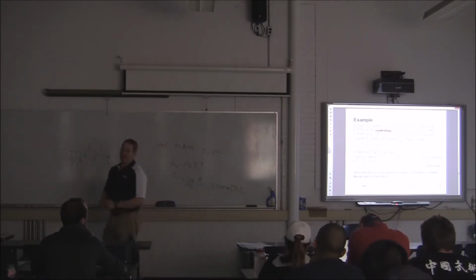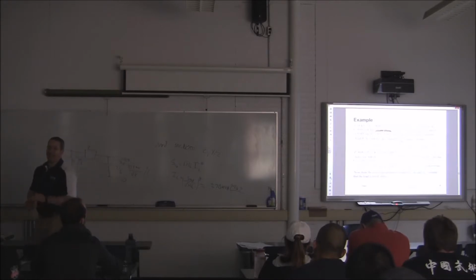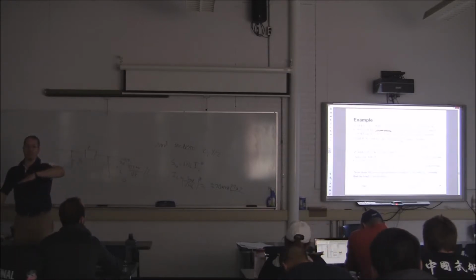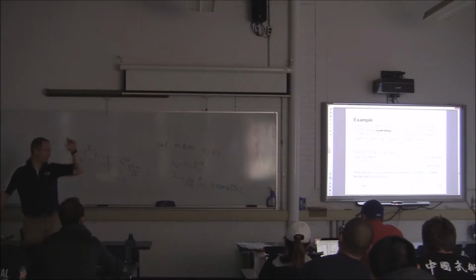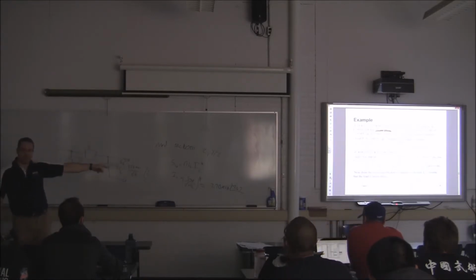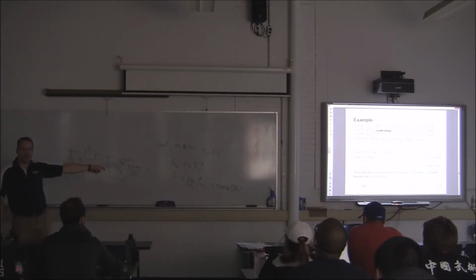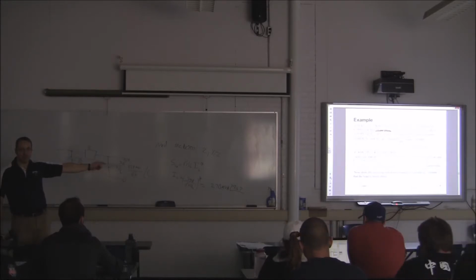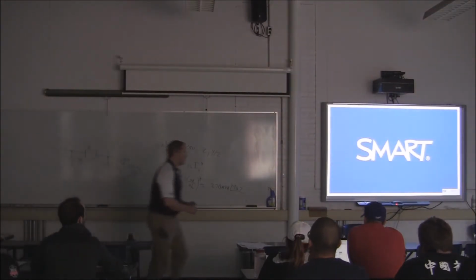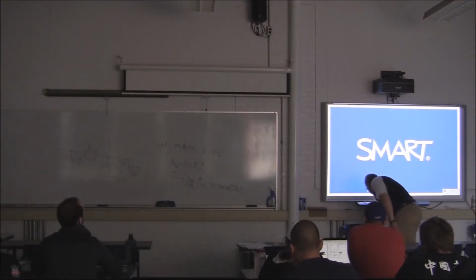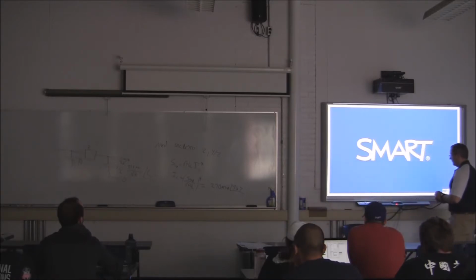Why did I put the negative 36.7 there? It is a lagging power factor, which means what? If it's a lagging power factor, the power triangle is flipped up. Then I've got to take the complex conjugate of that, which means I have to put a negative. I'm going to pause for a second because I'm relying on a lot of understanding of power triangles here. So I really want you to think about what I said and truly understand how I ended up with negative 36.7. Sorry about that.